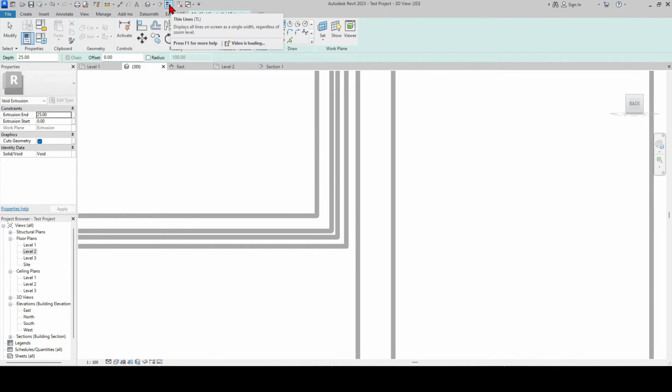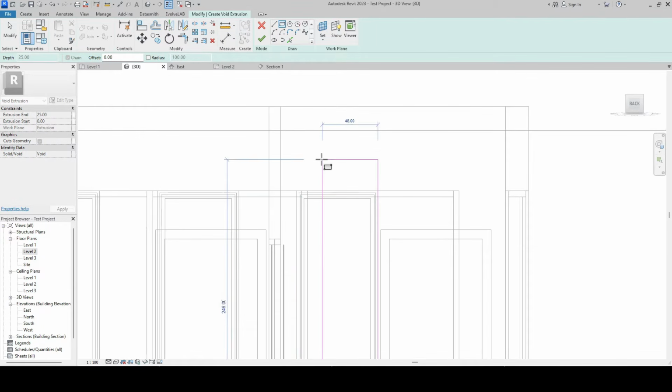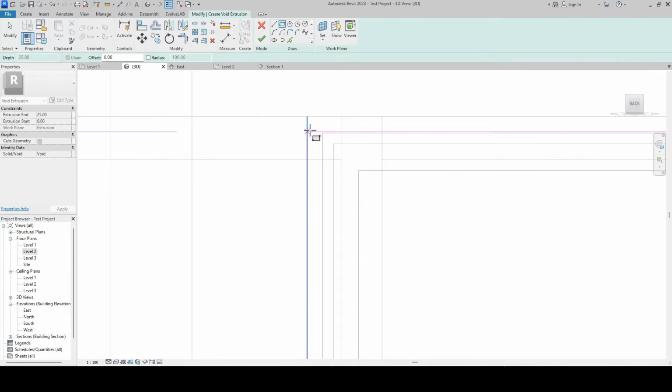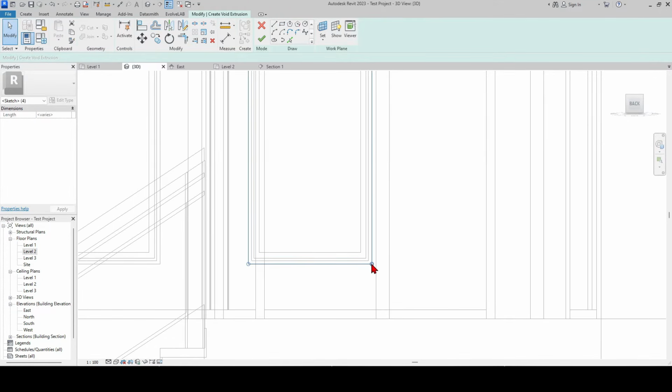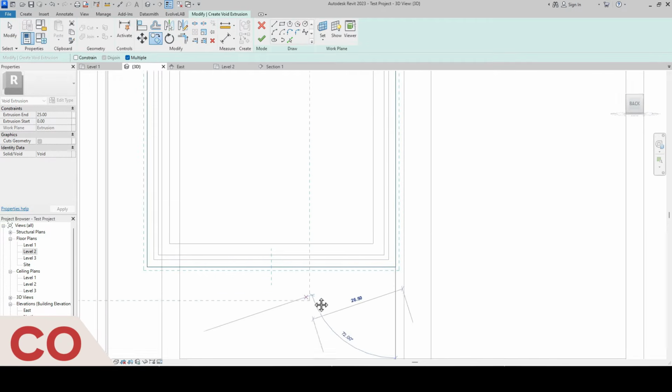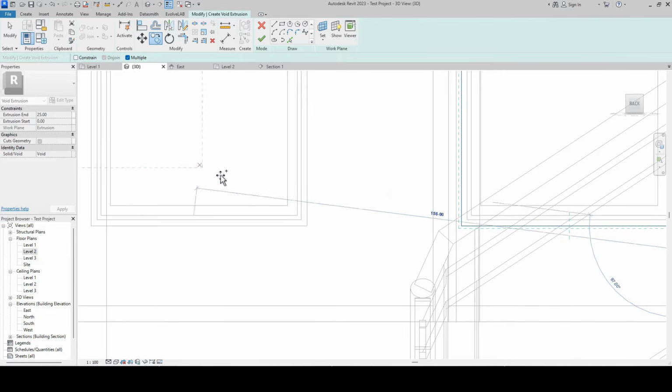Open thin line again for a more comfortable drawing. Then copy the other windows onto the other windows, referencing the corner point. Also, if you want to copy more than once, the multiple tab must be open.